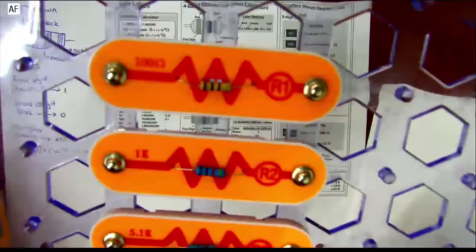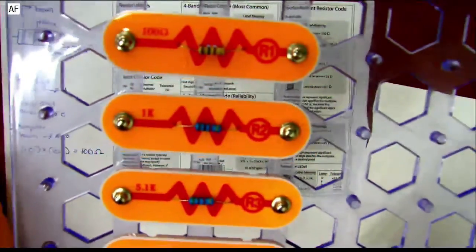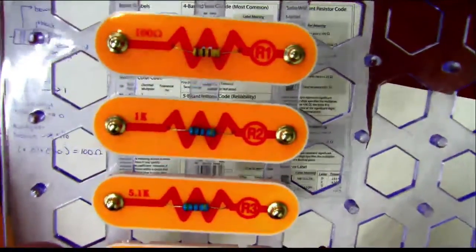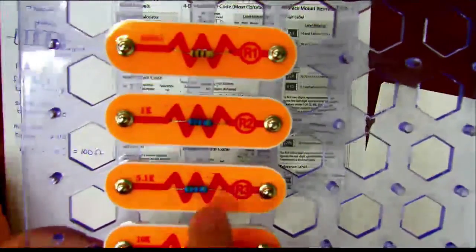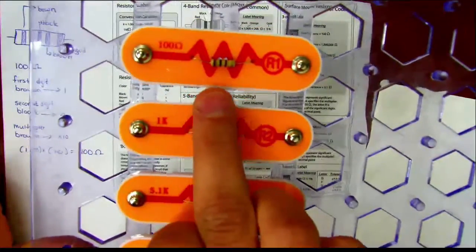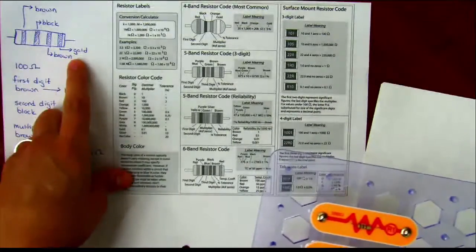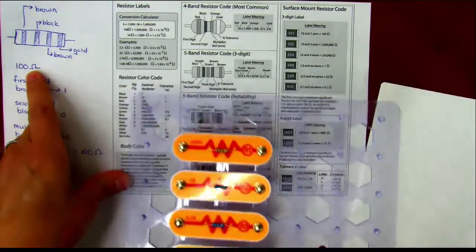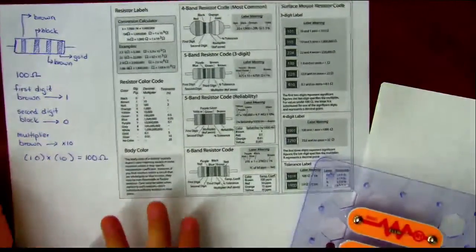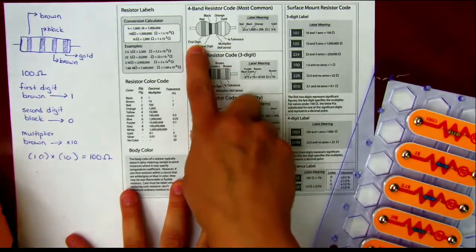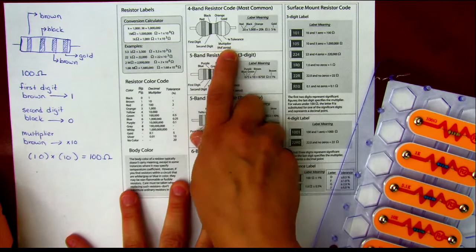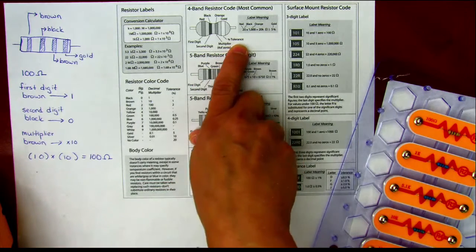All right. So if we look at this 100 ohm resistor, it has color codes across it that are hard to see, but we'll go through them anyway. He goes brown, black, brown, gold. It's supposed to be 100 ohms, but there's like a decoder ring. So he's a 4-band resistor: the first digit, a second digit, a multiplier, and a tolerance percent.